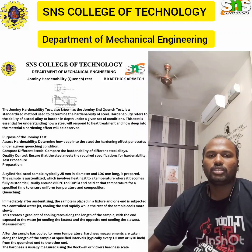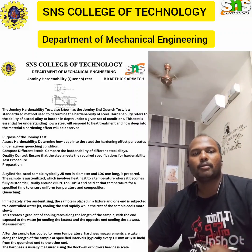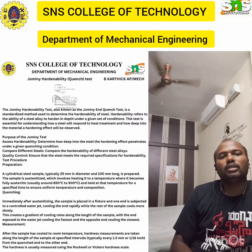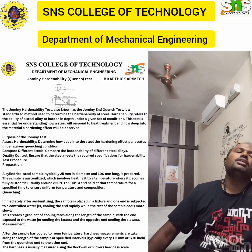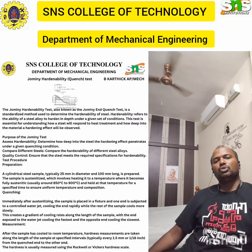The second one is quenching. Immediately after austenitizing, the sample is placed in a fixture. One end is subjected to a controlled water jet, cooling that end rapidly while the rest of the sample cools more slowly. This creates a gradient of cooling rate along the length of the sample, with the end exposed to the water jet cooling the fastest and the opposite end the slowest.